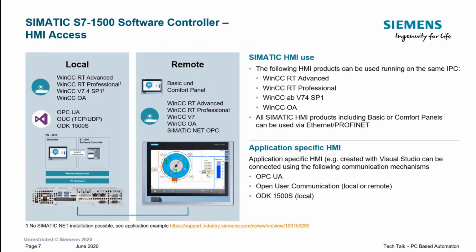Now, in terms of the operator visualization, we've got a nice little graphic of a touchscreen there. So we touched on how we can have these IPCs with a touchscreen on the front. So this slide just goes through how we can interface with these software controllers to give ourselves some operator visualization. And you can see it's quite a busy slide. There's quite an array of ways we can do this. So if we look at the box on the left, local, what that means is what can we install on the device that's running the software controller. So the Windows environment in this example for the IPC.